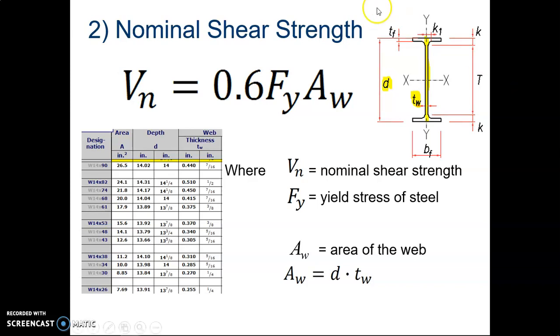So the member is not going to snap at the top part right here. It's going to snap in the middle where the load's actually being traversed through. So this right here, the unhighlighted portions, they're not actually supporting the load of a shear. They are there for helping with bending by creating larger inertia. So when we're analyzing what it can handle regarding shear, we're only concerned with the portion that's going to be traversing the shear load, which is the web right down the middle.